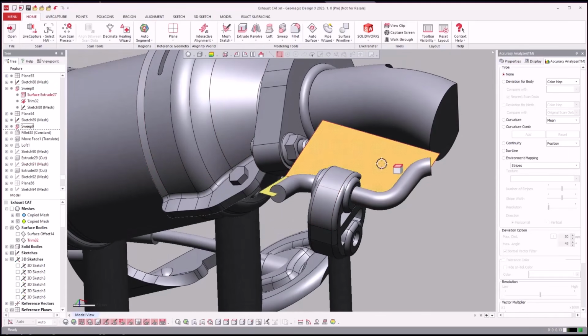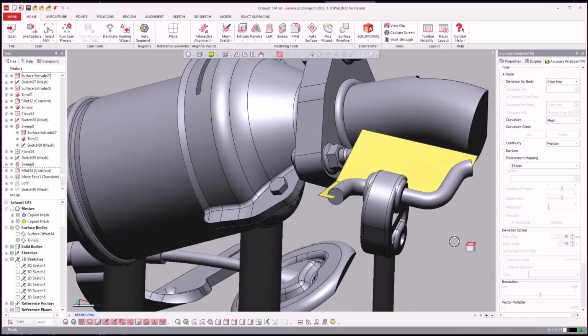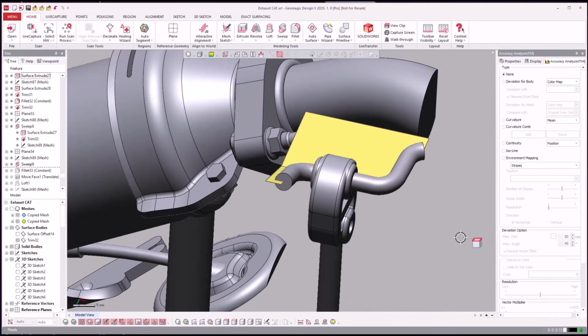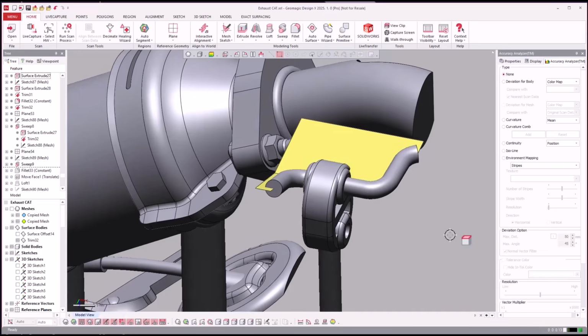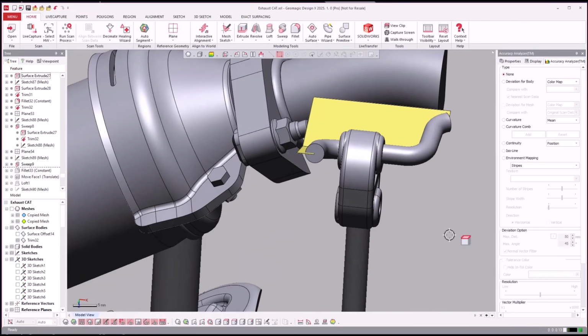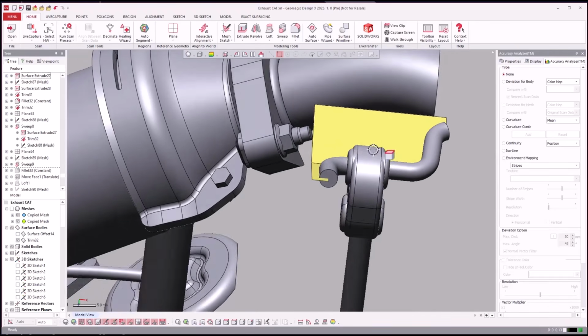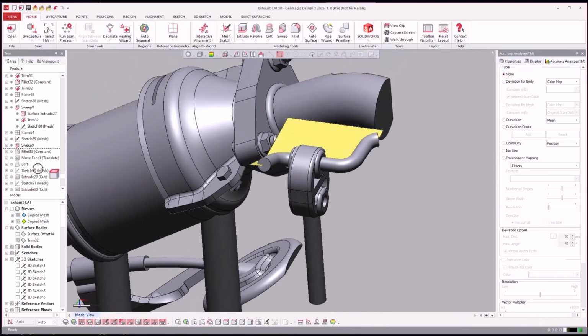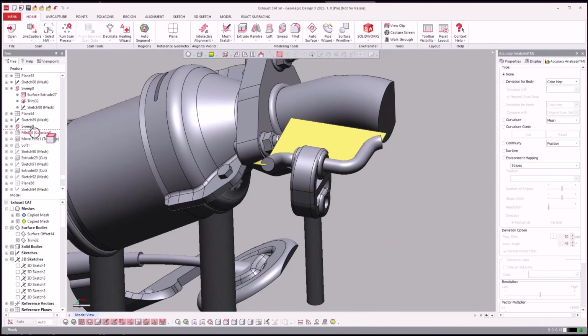But that right there is the tip of the day. Just to highlight this, that is a really valuable tool for your toolbox when modeling here. Sometimes line art 3D sketching is very difficult to break down and create stuff, but you can actually trim surfaces together to create that, and that's how we did it here, and it was very effective.